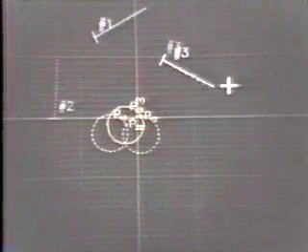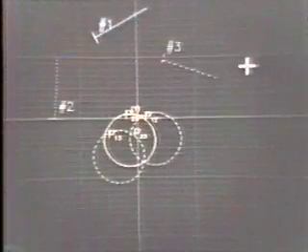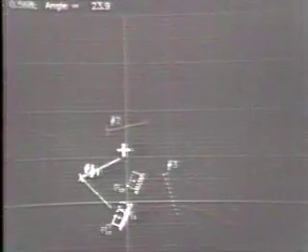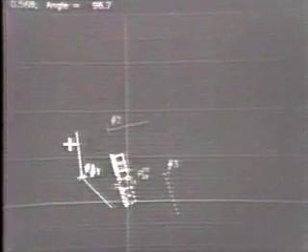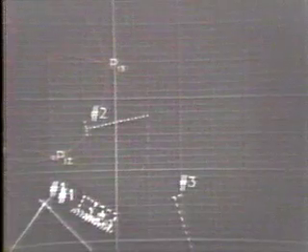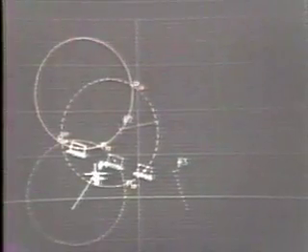The designer is now positioning a third plane symbol. Notice that 3 circular loci are also shown on the screen. These represent the loci of possible sliders capable of exactly moving the reference body through its 3 given design positions. As the designer changes the design positions, the circular loci change.